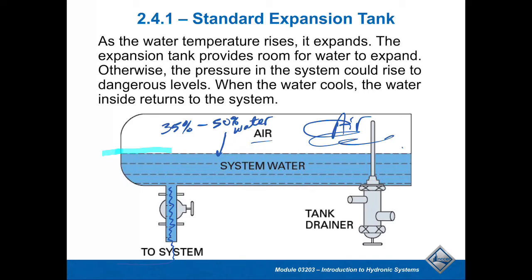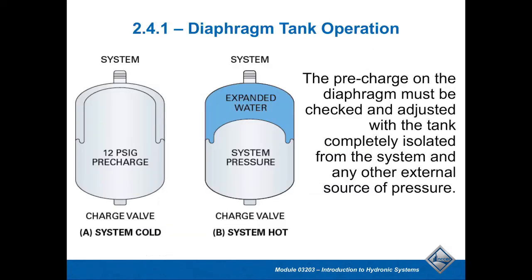The problem you have with these old expansion tanks is that over the time when you're not running them, a lot of the air in the tank tended to migrate and be absorbed into the water that would be in here. So as you took some of the air out of the tank and put it into the water, the pressure in the system goes down, and the fill valve will make up that water pressure and build it back up. Eventually, the problem you run into is a lot of these tend to get, let's call it waterlogged.